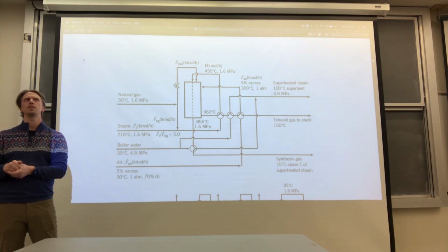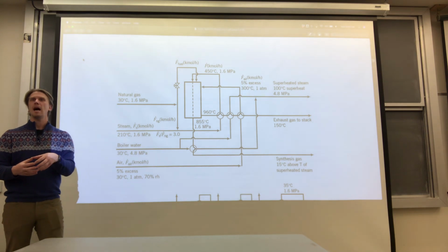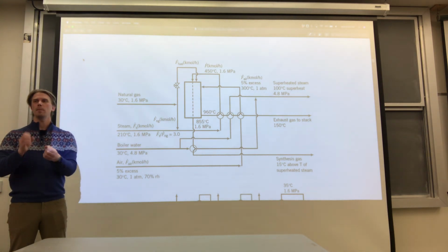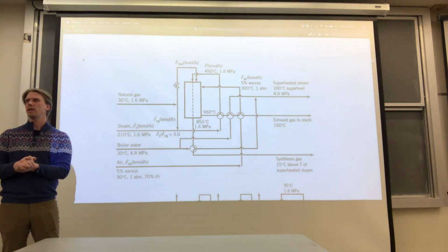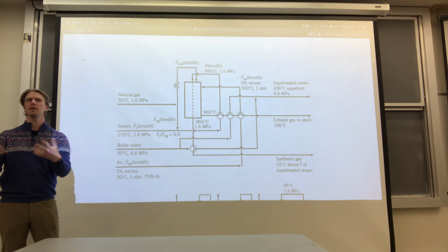So if you ever have a system that's running out to higher pressure, or if you have a reactor that has a burst disk or something like that, like, oh, there's a pressure hiccup in the system, I need to lower the pressure, you want to be able to, in an emergency, send that out to the flare. And then you burn it so that it doesn't release any harmful chemicals. So the flare is an important part.